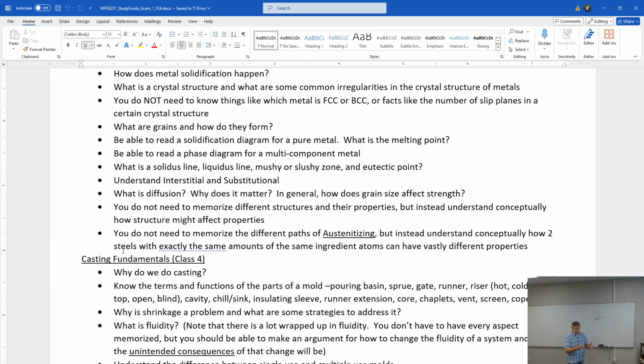And the difference between those is that if it hits another dislocation, we can probably get it to form more by putting more stress in. We can get it to continue on. If it hit a set of interstitial impurities, then we can reset that by going to the range of recovery, where we heat it up to the warm working region and we disperse those interstitials, and that's the way that we gain some ductility back and we're able to form the part more after we recover it.